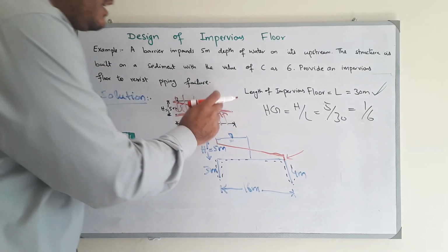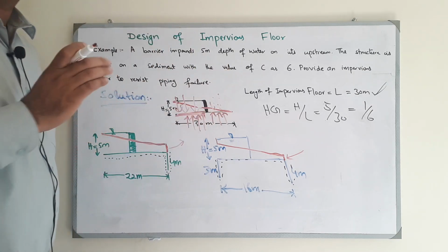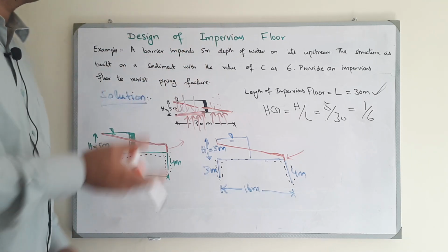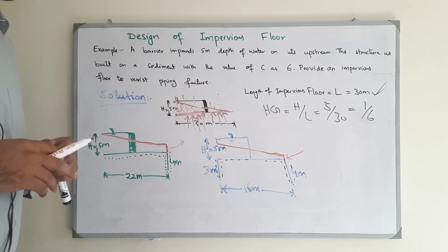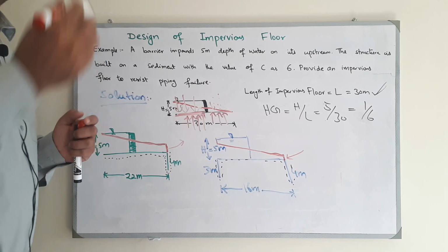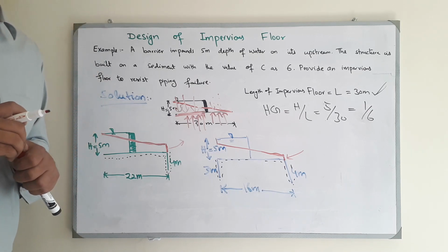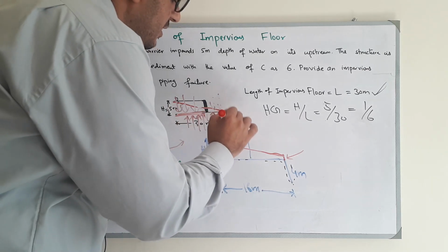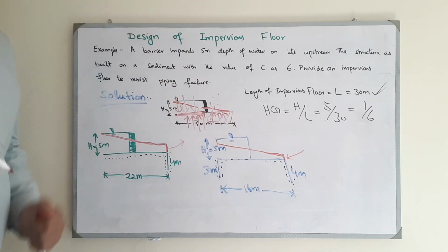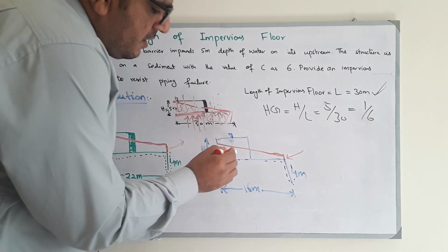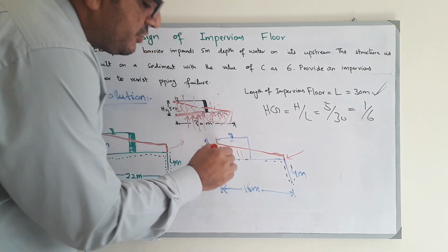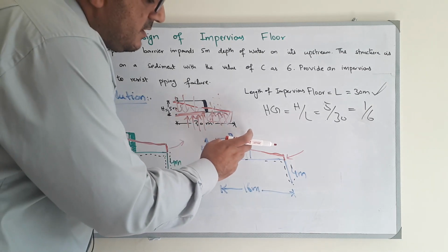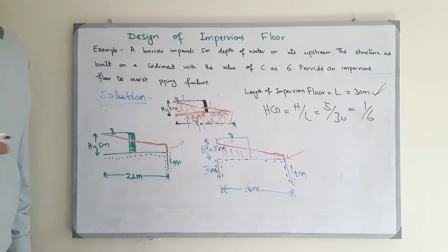But at the downstream section, you have to provide a thickness of the floor according to Bligh's theory formula of thickness, which we have studied in the first section of this video and derived in the previous part of our Bligh's theory lecture. So now let's say this residual pressure is no concern for us because it is counterbalanced by the water.